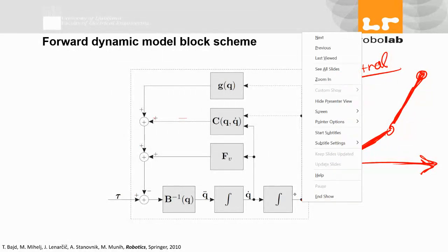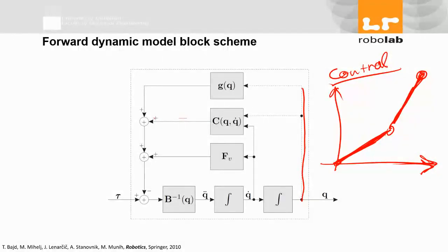That's why it's only a function of theta, or angle. Based on theta, and the sizes and masses of my robot, I can do basic calculations to find the effect of gravity at each angle, for each selection of different angles of my robot. I can find the gravitational force, which also will be subtracted from my force.